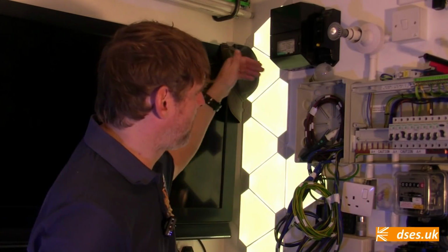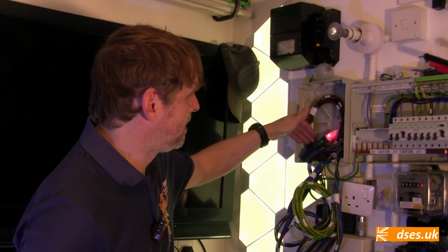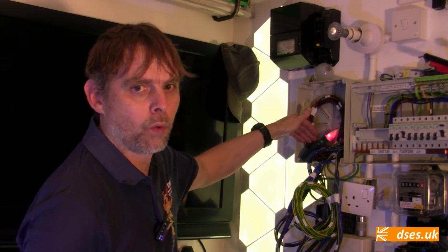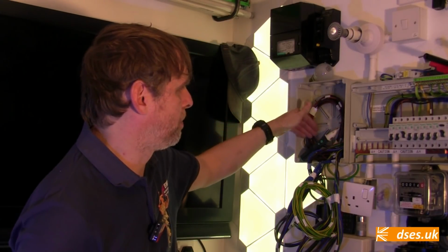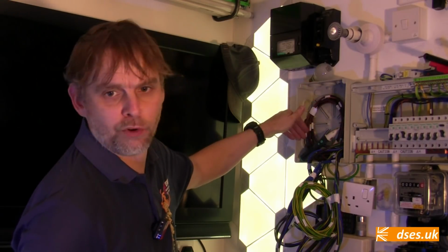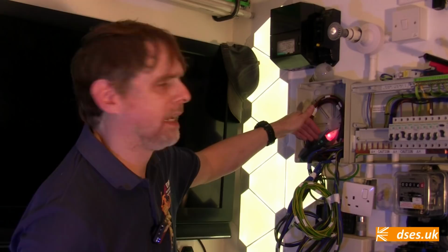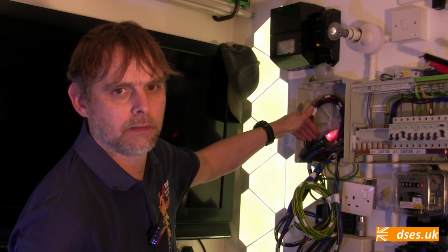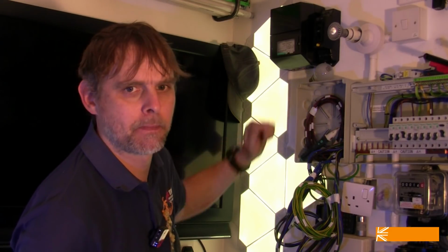That's because it is no longer capacitively coupled to earth through me. If I place my body near it without actually touching it, then once again a capacitive link is formed between it and me, and the current can flow through me to earth, and the indicator indicates accordingly. Fucking magic, eh? To get this to work without my presence, I need to couple it to earth via other means, and of course I can use one of the CPC wires that's right here and is a better path to earth than I should ever be.